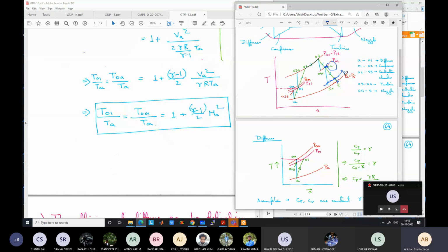If the nozzle is choked, how will you find the exit velocity at this point? And how will you find the exit conditions? Now we are coming to today's discussion. Sir, Mach number is 1, so we can get the exit velocity. How will you get the exit velocity? If Mach number is 1, what is the equation of exit velocity? Root over gamma R T.